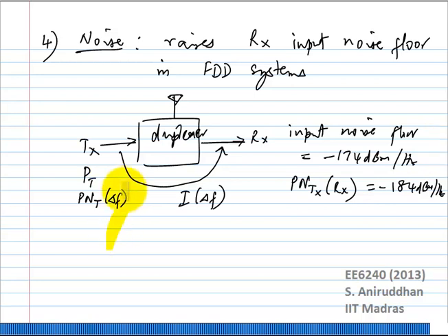then you will be able to derive what absolute phase noise power you need at the transmitter, because you know the worst case isolation of the duplexer, and you know what the maximum Tx power is. At that point your noise floor will also be maximum, right? And therefore you can calculate what the phase noise spec of the transmitter itself is at a certain offset. So that is the way you would work backwards. How much desensitization can you actually survive at the receiver? What is the isolation of the duplexer? How much phase noise do you need at the transmitter output? And then you will just have to design the transmitter for this particular specification.